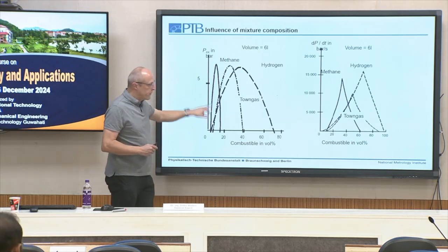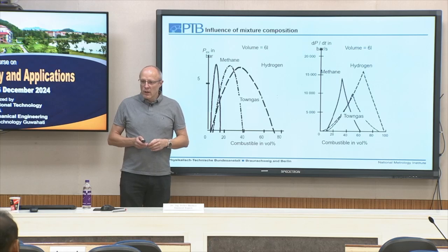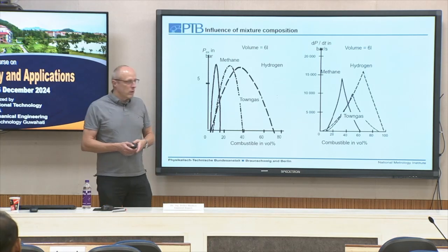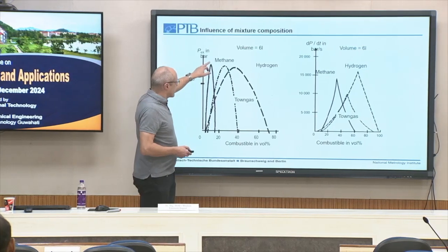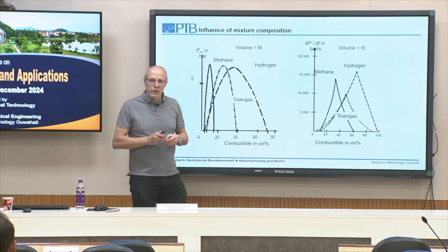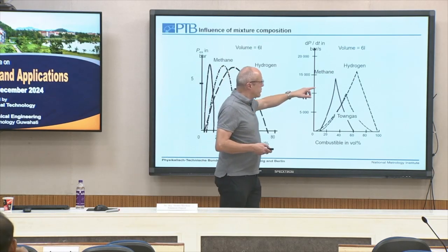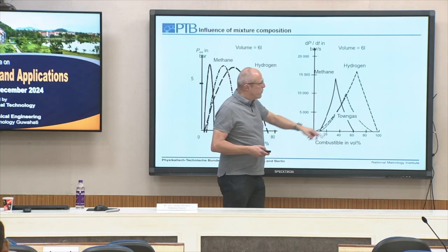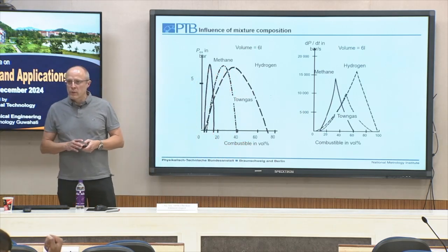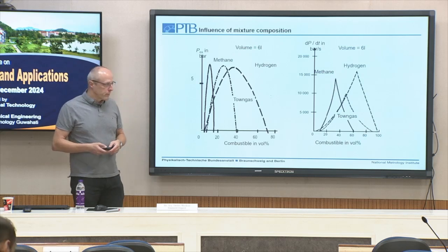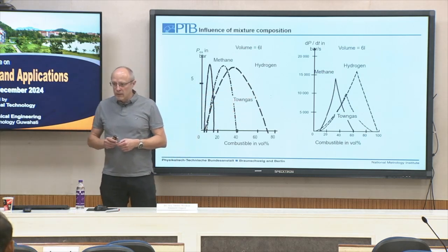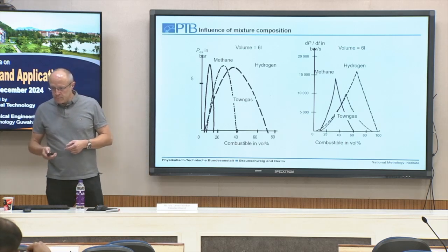So you see within the flammability range, it again strongly depends on the mixture composition which pressure we yield. Of course, the temperature alone depends strongly. Therefore, the pressure has to depend also. And of course, the combustion velocity, so the flame velocity we have seen already, depends on the mixture composition, and therefore the pressure rise, of course, also depends strongly on the mixture composition.